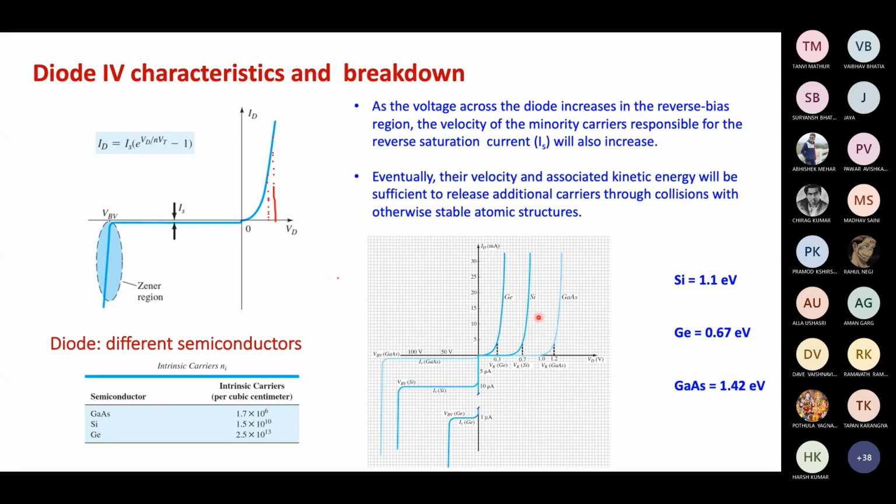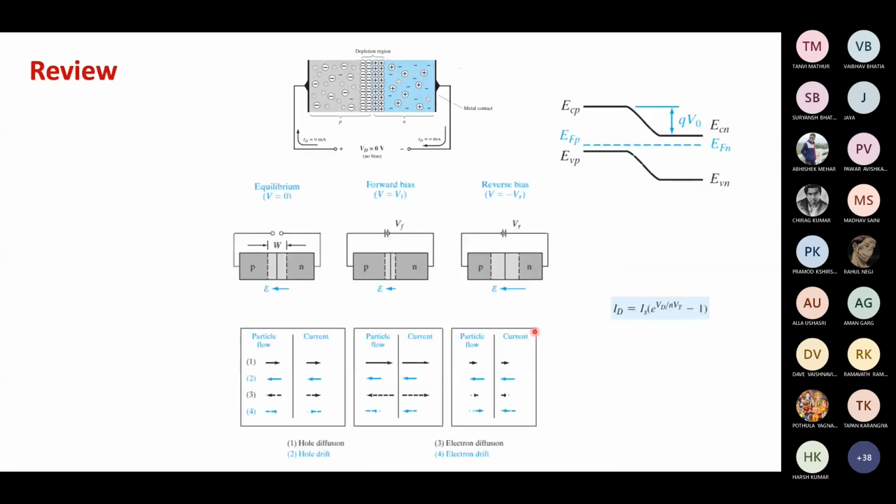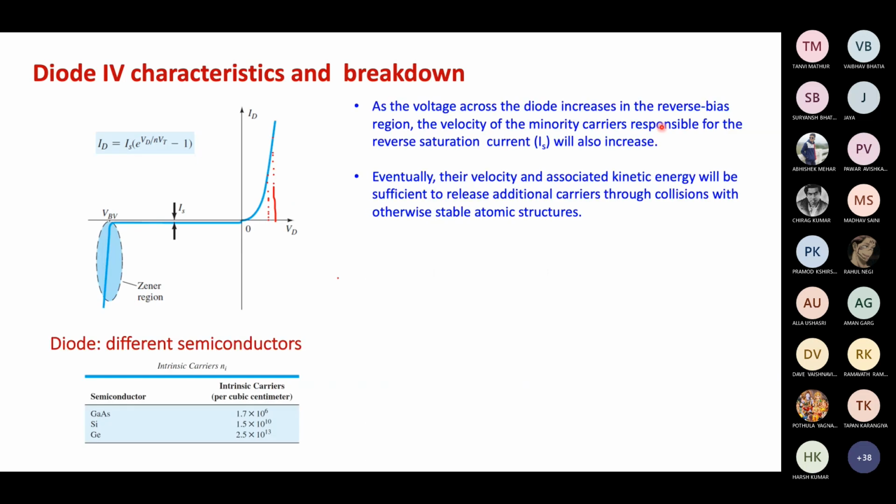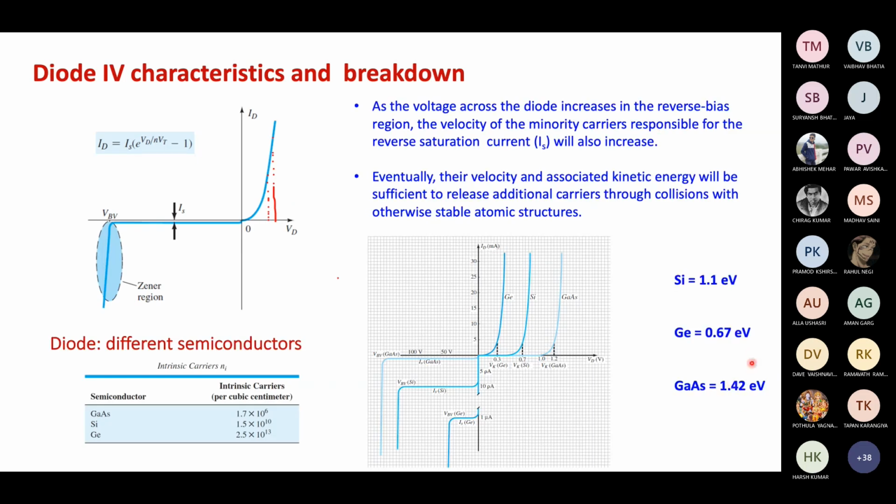Yes, that's also an interesting thing to think about, and that depends on the depletion region and ultimately this barrier that is created in the diode. So for the same doping, let's say if we dope silicon and gallium arsenide with the same amount of doping, this barrier height would be more in the case of gallium arsenide, and the reason for that is this band gap.